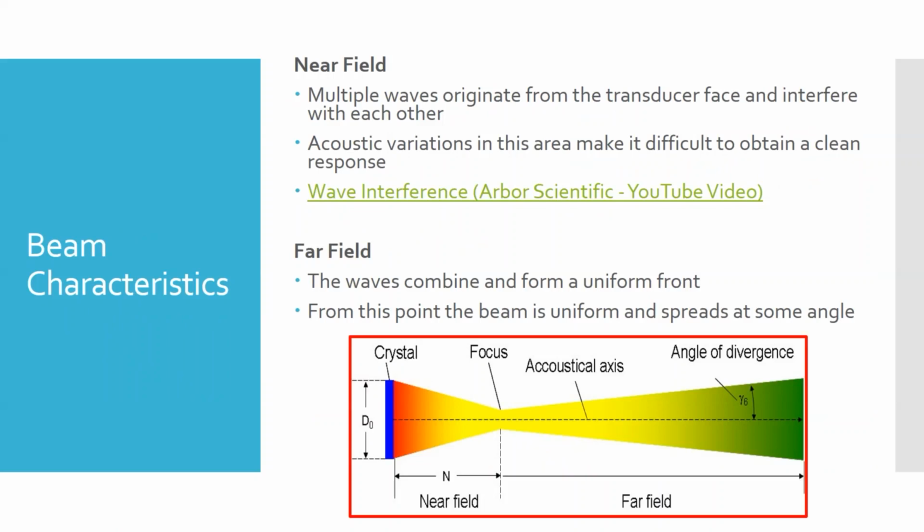So ultrasonic testing is rarely used for surface inspection directly in front of the probe. Now, there are ways to do surface inspection where the probe is not right above the area, where you send the wave along the surface of the part, but you're outside of that near field.